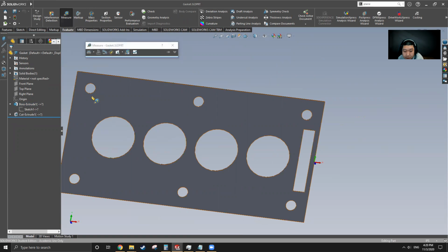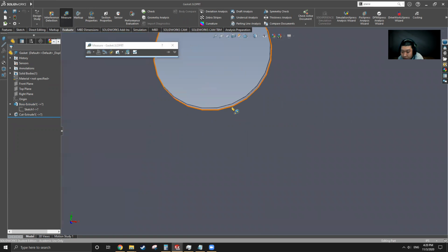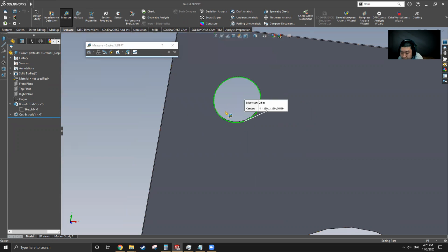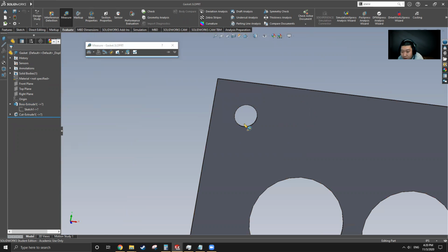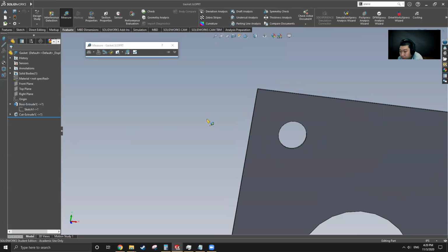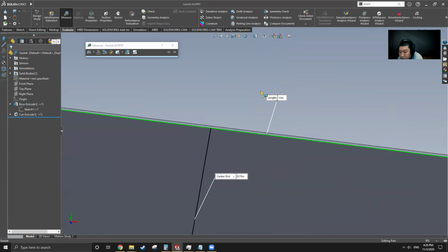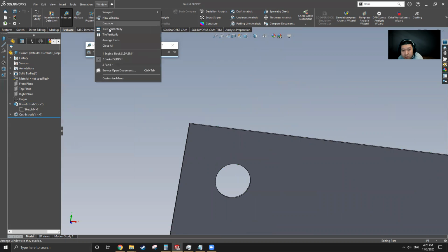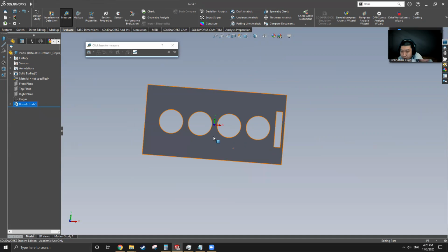And now we make 6 holes. The holes must be bigger as well because the bolting is going to go through. So the diameter, oh no, actually the diameter is 0.5. And the distance is 3/4 from both edges.